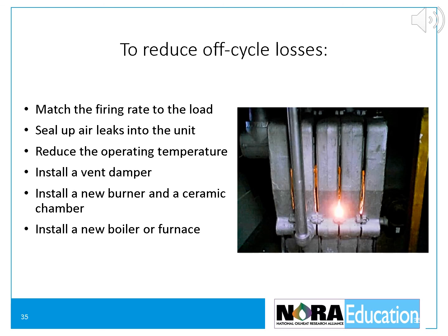Sealing up air leaks into the heat exchanger will lower idle losses as well as lowering the operating temperature of the unit. Restriction of off-cycle airflow by the burner head can reduce heat losses. Generally, older burners were designed with open combustion heads that provided very little resistance to off-cycle airflow. In contrast, the restricted air passages in a new high-speed flame retention burner reduce off-cycle airflow and thereby reduce heat losses. New oil vent dampers are a way to reduce off-cycle losses on older boilers and furnaces.